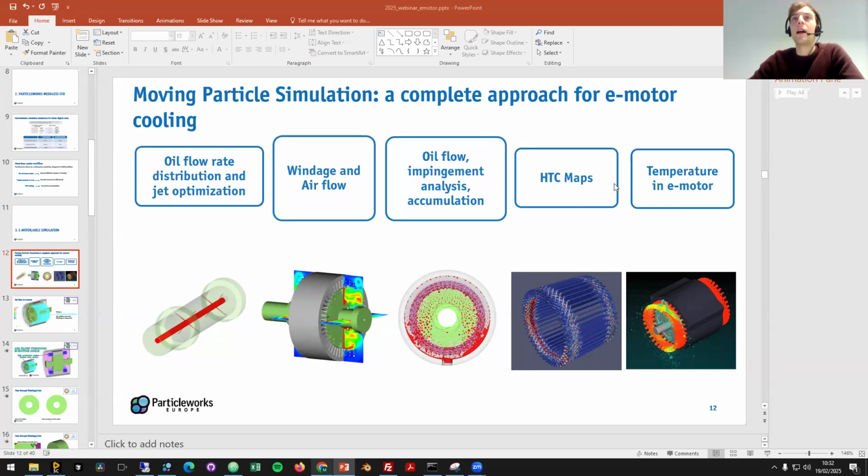So we could have a coupled or a decoupled CFD to thermal model. It depends. Sometimes we want to study the solid temperature after the fluid simulation, so it's what we usually saw and we usually suggest. So there is a transfer of information about boundary conditions from the CFD Particleworks result to the solid solver, again integrated in Particleworks. So there's no loop, I would say.